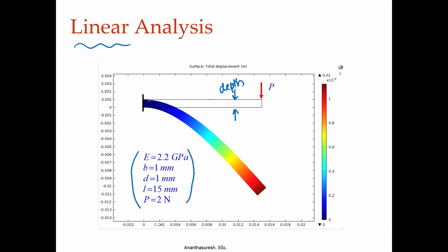You do not imagine that a beam such as the one shown in the black lines, when I apply force P over there, that is actually P should be here, right. So, in this case P is not there. When P is here, you see that it seems to be expanding a lot as if it is heated. That is the unrealistic thing that linear analysis gives us when the force is large.